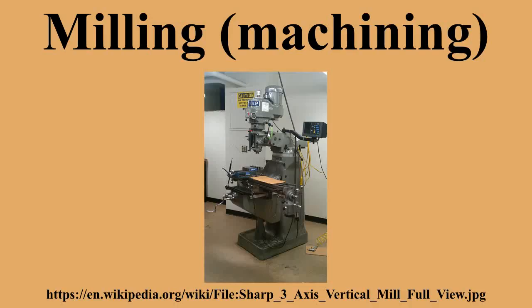Computer numerical control. Most CNC milling machines are computer-controlled vertical mills with the ability to move the spindle vertically along the Z-axis. This extra degree of freedom permits their use in die sinking, engraving applications, and 2.5D surfaces such as relief sculptures. When combined with the use of conical tools or a bull-nose cutter, it also significantly improves milling precision without impacting speed, providing a cost-efficient alternative to most flat-surface hand engraving work.